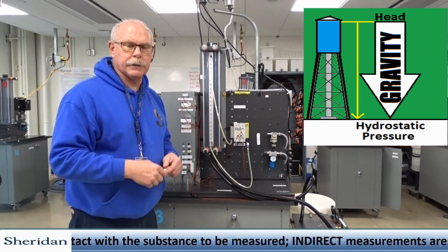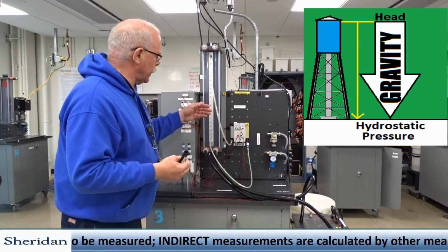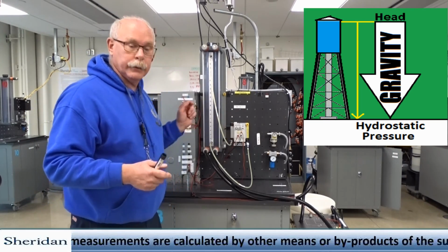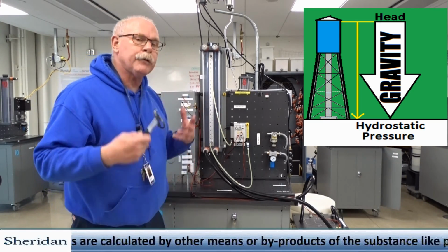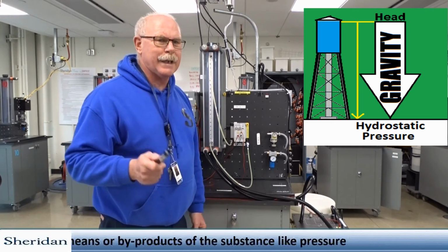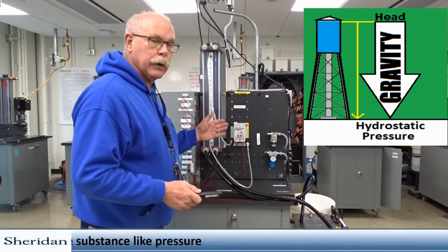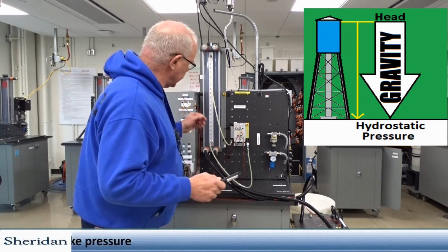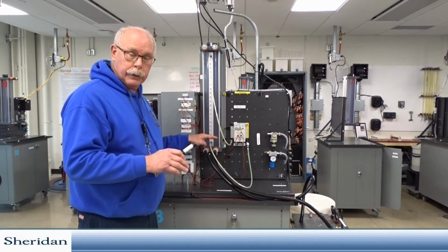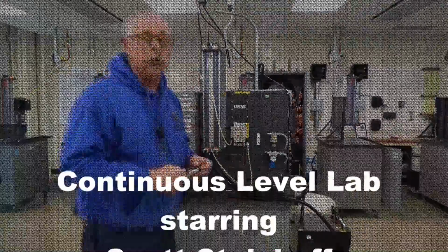This is a pressure transmitter, so it has to take into account hydrostatic pressure from the top of the liquid to the port on the transmitter. Now, if you have to move this transmitter, it is very important that you recalibrate. You have to recalibrate the transmitter for the new level. So always keep this transmitter on the same level that you originally installed it on. If you have to move it, you have to recalibrate.